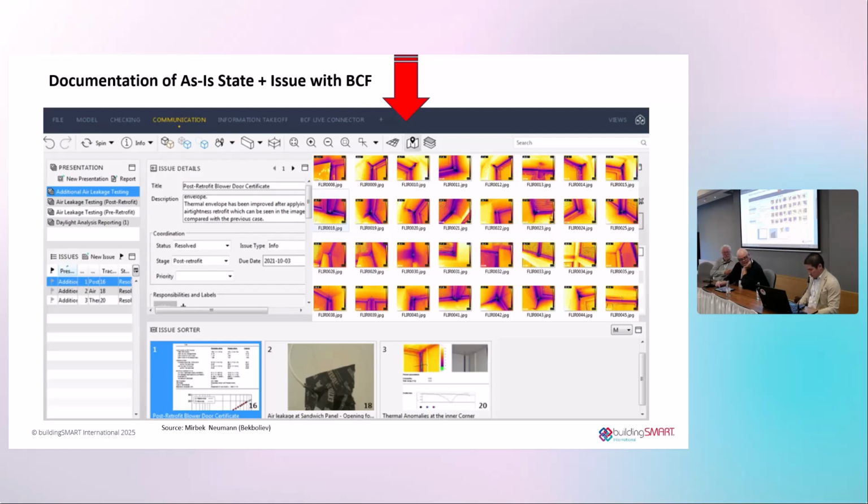check thermal imaging. And this is the typical example. It will have, even in this building, probably all those issues related to thermal bridging and air leakages. And you cannot see it with the naked eye. You can use a thermal camera for that and document it. Thermal camera means, in practice, you have your paper, you match that, and camera documentation.